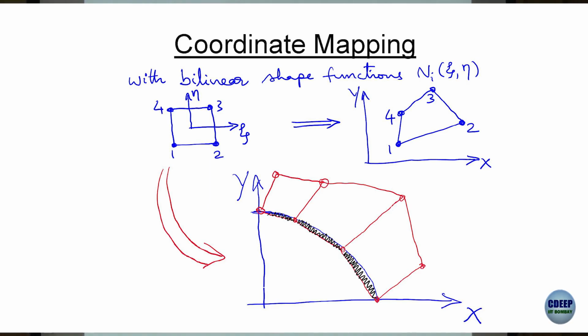So based on that, you can see how much material you have added in your finite element model, extra, compared to that hole. Circular hole did not have any material. So this area, you can see, the blue is the actual curve, finite element is the line. So therefore you have added this much material, which will shrink as you take more and more elements, and so that approximation would become better and better.